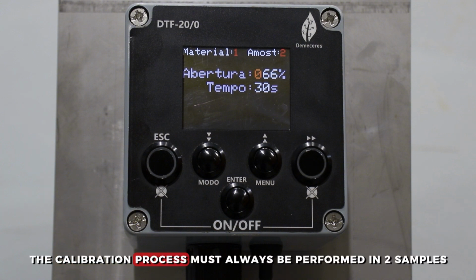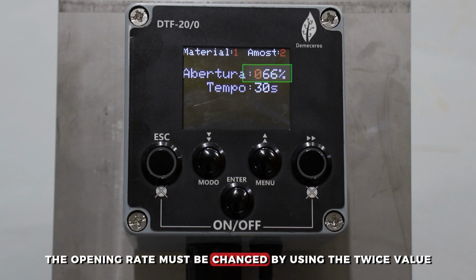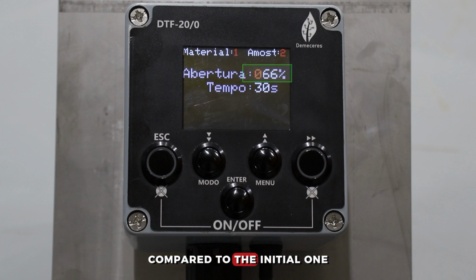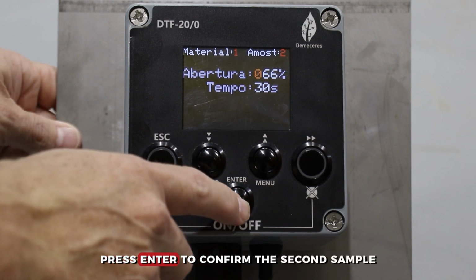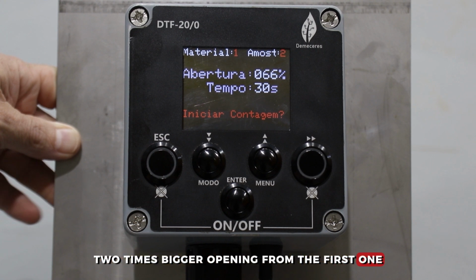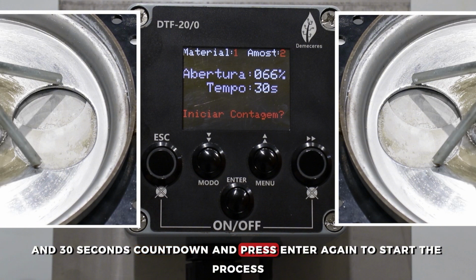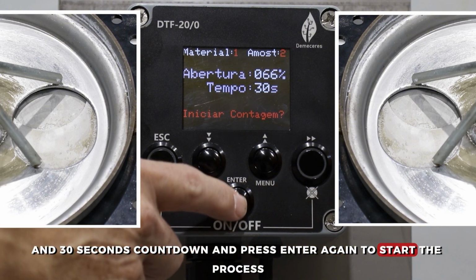The calibration process must always be performed in 2 samples. For the second sample, the opening rate must be changed to twice the value of the initial one. Press Enter to confirm the second sample, with an opening 2 times bigger than the first one and a 30 seconds countdown. And press Enter again to start the process.